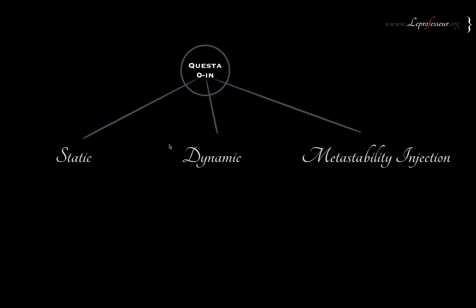The assertions are generated when you use the dynamic mode of the tool, and those assertions need to be compiled along with your regular test bench. You can use either the Questa simulation environment, or you can use those assertions with VCS or any other third-party simulator.